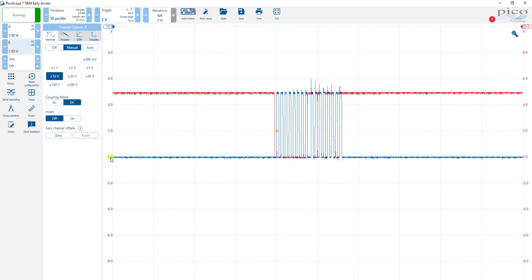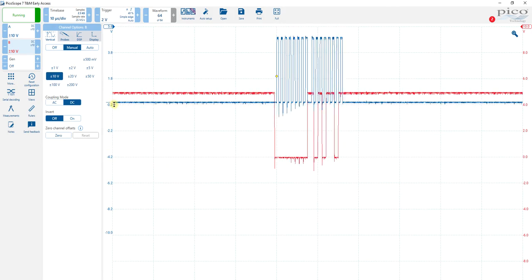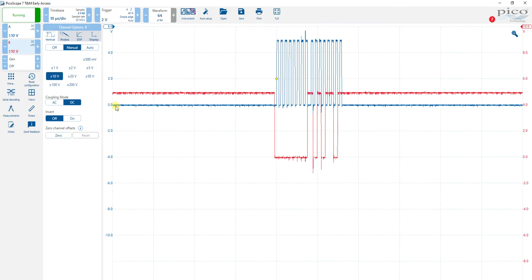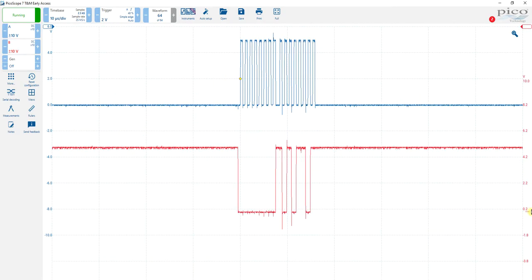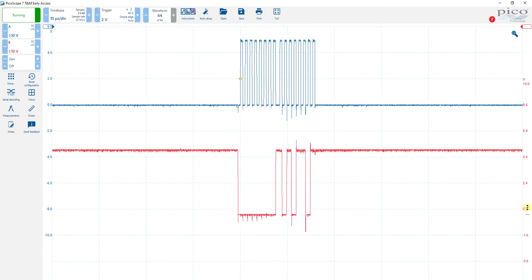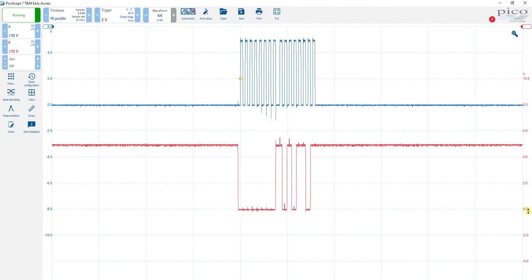So to get rid of that, you just drag this up here and get it so that this part shows 0. Same thing for this red line, drag it down. It's probably easier to drag on the 0 and just bring it down, but don't have it say 0.4. It's not easy to read that way. Have it say 0. So this one says 0. So the red line scale is on the right. The left scale is on the left-hand side.